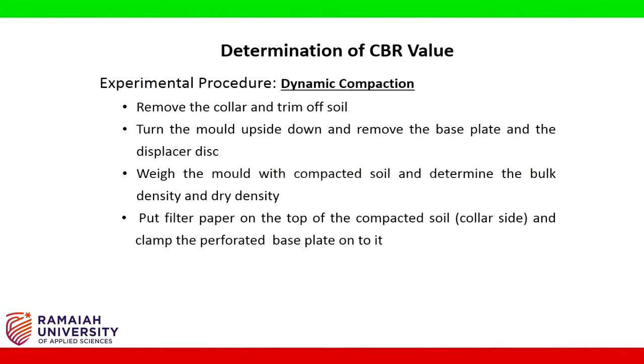Put filter paper on the top of the compacted soil, that is collar side, and clamp the perforated base plate onto it.